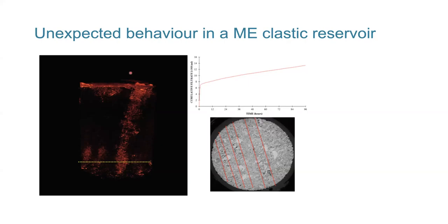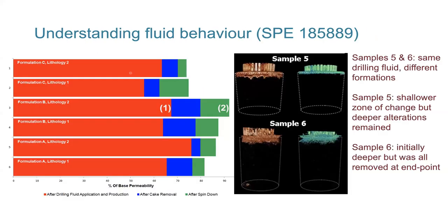So this mud was optimized for the middle pore throat, and in the maximum pore throats it went down there, and essentially this drilling mud damaged the best permeability zones. So if they wanted to optimize it, they would have to look at bridging it properly for the larger pore throats, and that was a conclusion that we could only get from this visualization technique saying where it went. And I'm just going to show you a couple more examples before we stop.